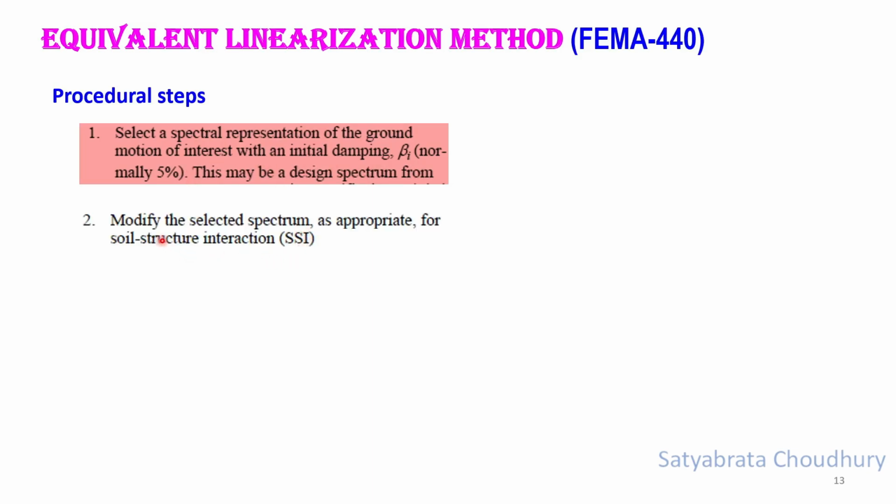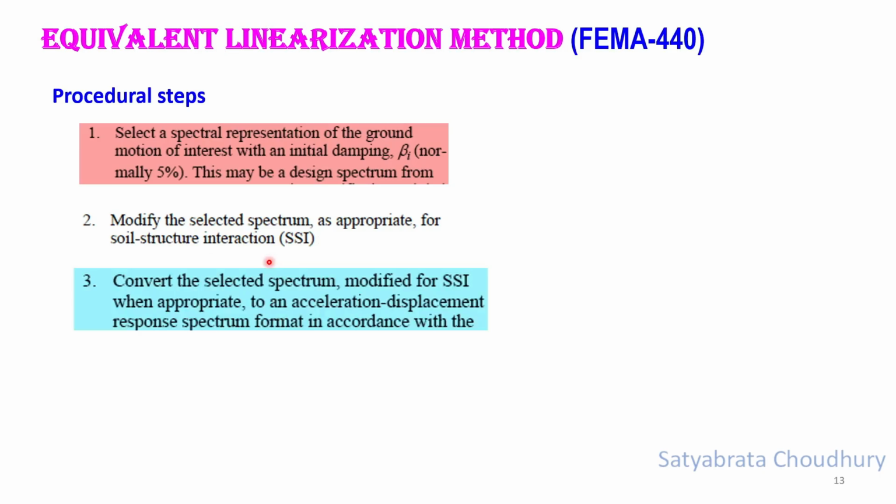Then modify the selected spectrum as appropriate for soil structure interaction. This we have not discussed so far in the video. With soil structure interaction, your structural response changes, also ground motion may change, so that modification is done here. Convert the selected spectrum, modified for SSI when appropriate, to an acceleration displacement response spectrum format, that is ADRS format, which we have discussed in previous videos.